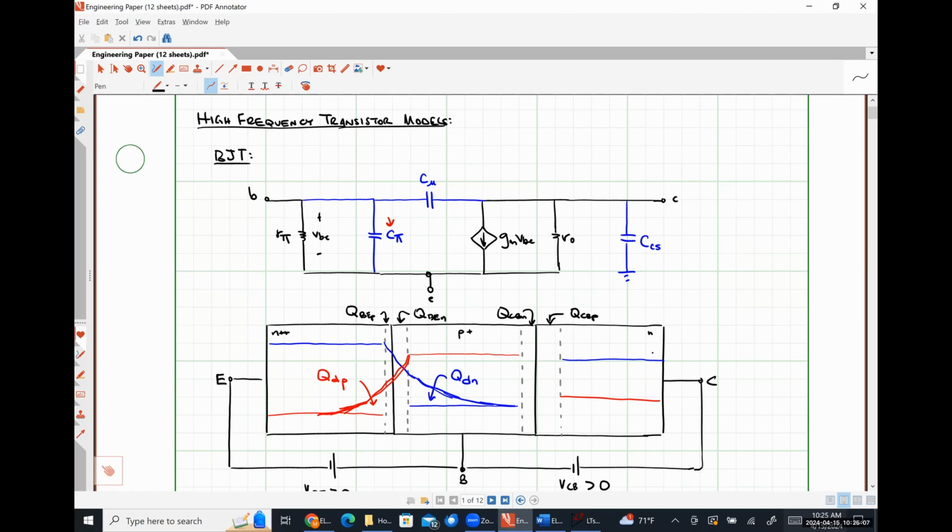which is between the low frequency response and the high frequency response. And that is the region of the bandpass filter where the amplitude is effectively constant. What we're about to be looking at is what happens when we're below midband frequencies and what happens when we're above midband frequencies to make sure that things don't go too wonky. And largely speaking, in an open loop configuration, they won't.